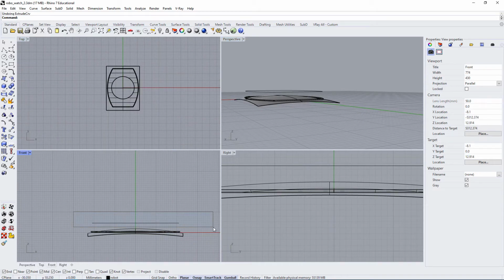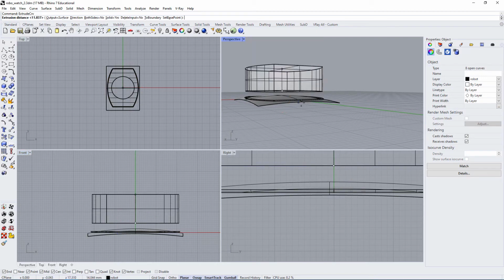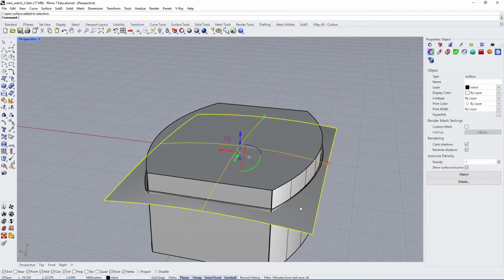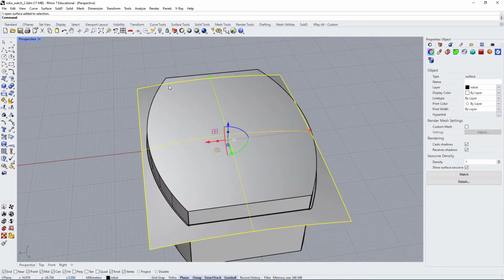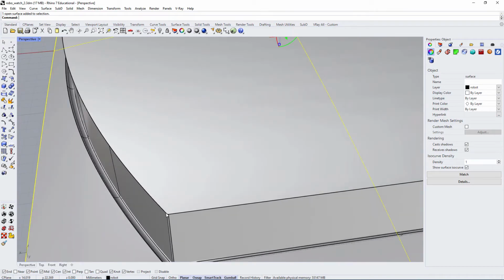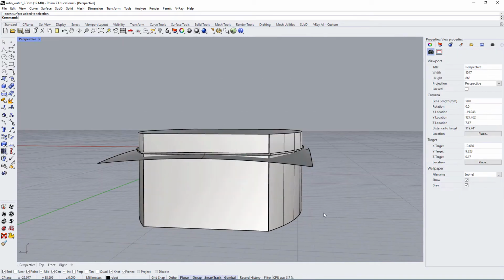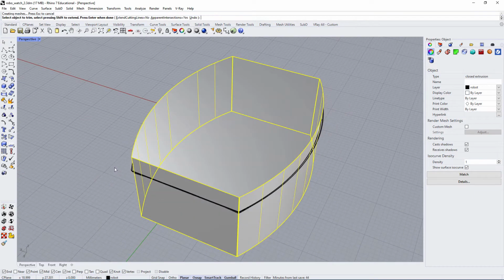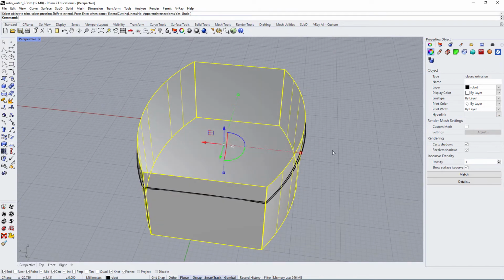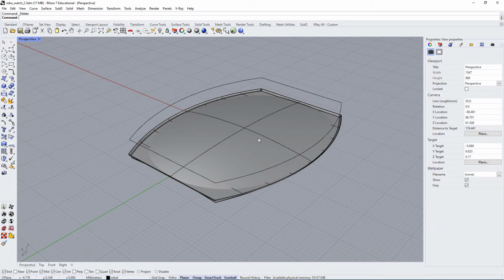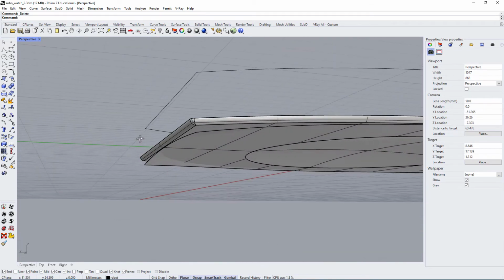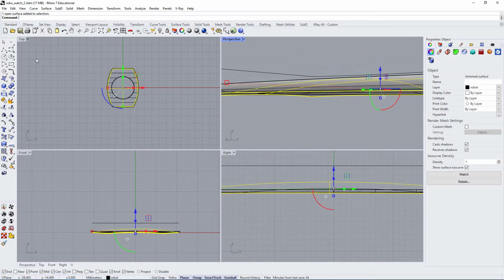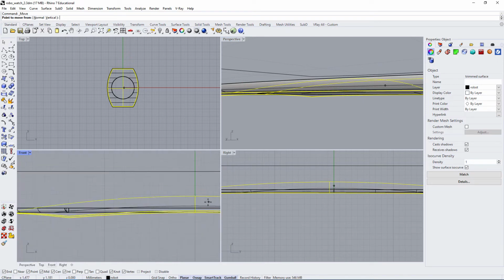So yeah, we can extrude all of these curves, and we can use that as a construction to make this four-sided surface into this more complex surface that has four sides and also four corner surfaces. So let's do this, select this surface and trim anything that is outside. Okay, it looks like it broke the history, which is completely fine. And we are basically done. So we're done with that major surface. It's a very complex major surface. And now we can work on our transitional surface.